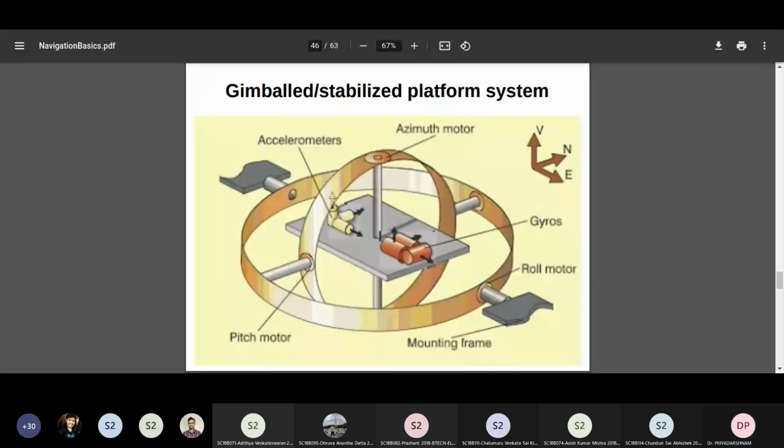When we discuss the basics of sensors, at that time we will introduce drift. If you keep on rotating at some rate, let us say 10 degrees per second, it will not measure 10 degrees per second, but it will keep on changing. That is called drift of the gyroscope. The drift, whatever change is there, gets integrated because it is encountered in your measurement, and the acceleration will indicate it indirectly. So that will give you a wrong navigation solution.